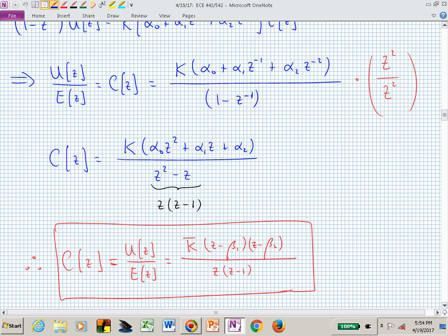So if I say I want you to design a PID controller for this system, immediately you can put a pole at 1 and a pole at the origin, and now you have total freedom to locate 2 zeros. And then you can crank up the gain, K bar, to put you on the root locus where you want to live. But you want to pick the beta 1 and the beta 2, your 2 zero locations, such that your root locus is in the shape or pattern that you hope it to be. This is now our PID controller.